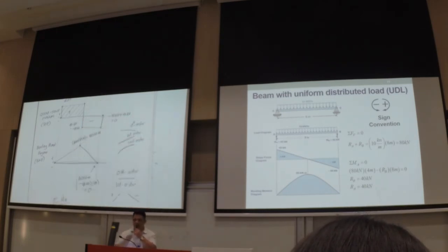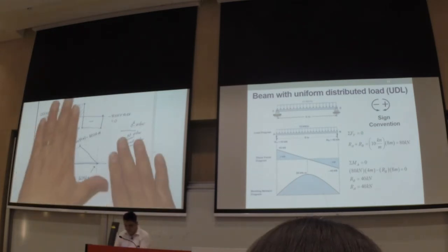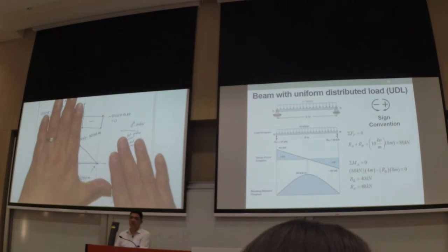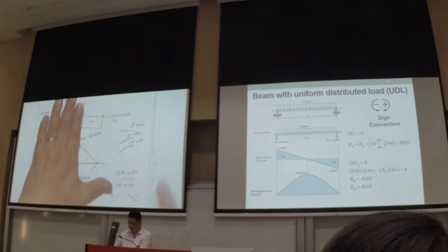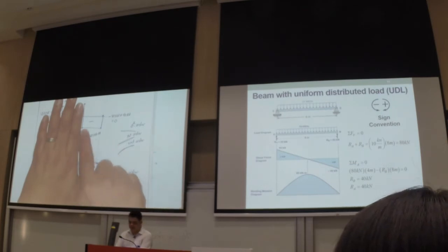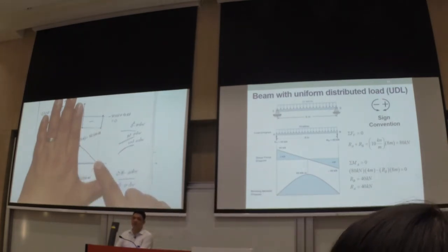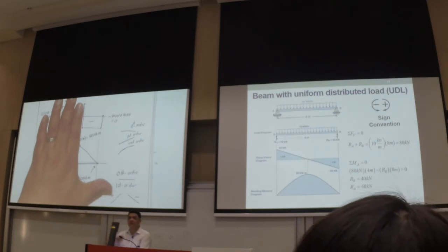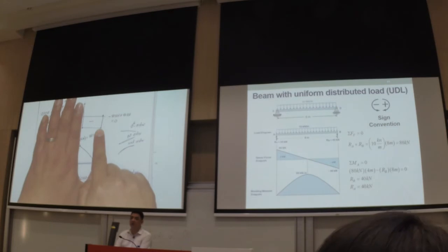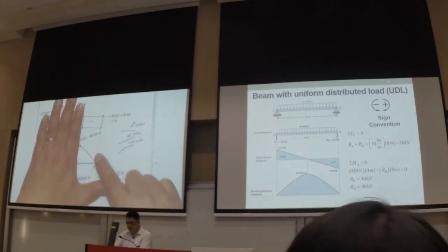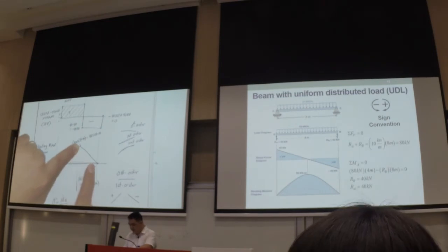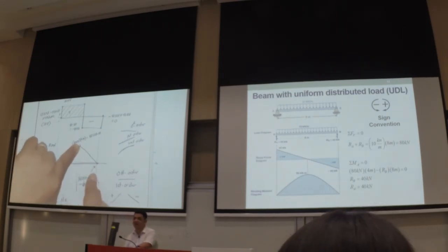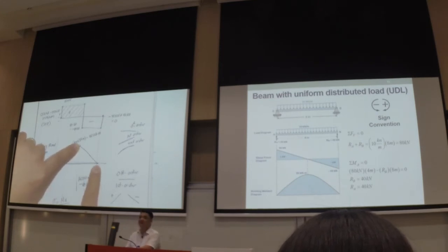Now, once you have this point here, you move to the next block. So why are we going down? Because based on our convention, this is negative, meaning we will be going down here. This is a 0th order, so this one becomes a 1st order. So we go by order. The lower we go, the higher the order. In this case, this one is a 0th order, negative, so we go down. Our starting point will be that point there, which is 160 kilonewtons. We can go down until here, we don't know, but because I already have an initial idea that it's going to end at 0, I just end it there at 0.